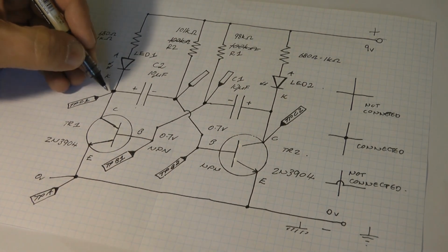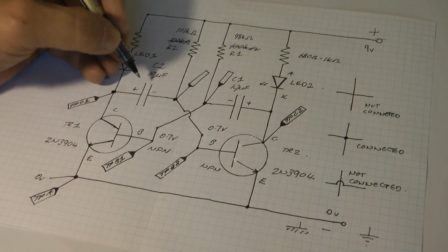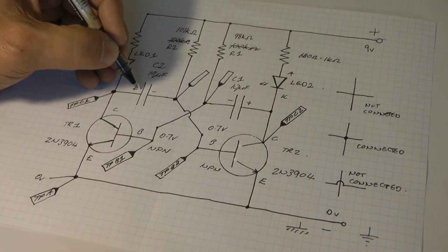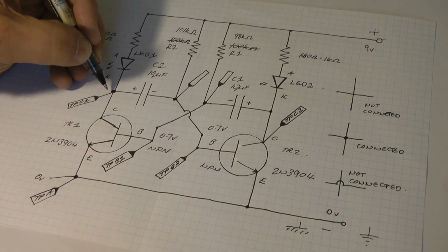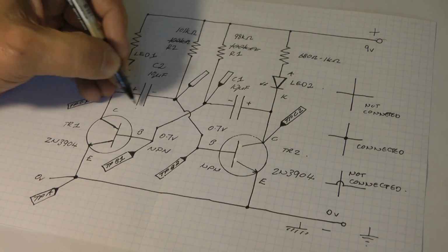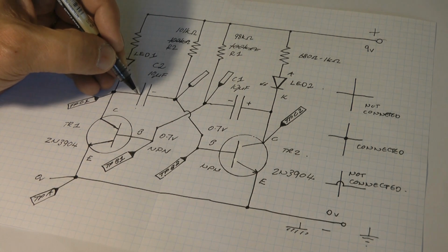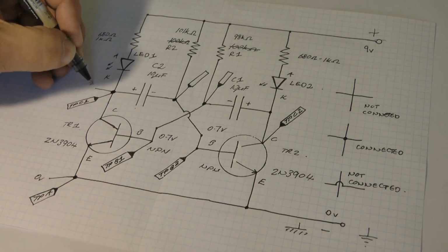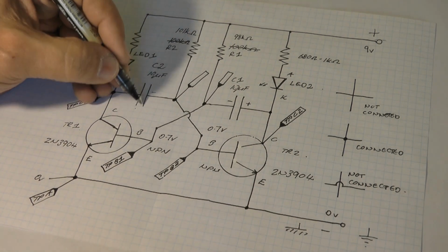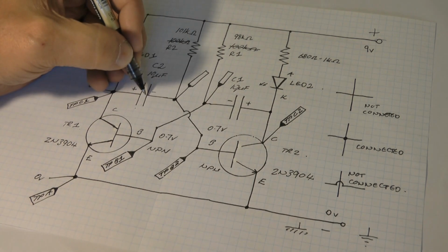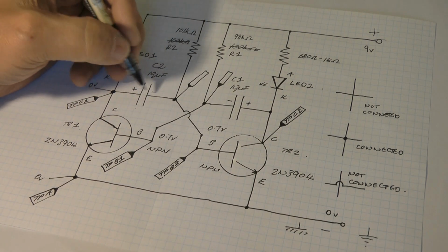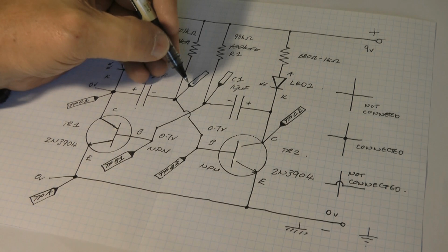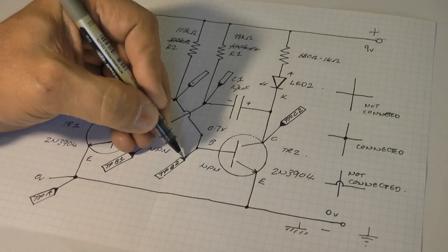Because test point C1 is dropped to 0 volts, whatever voltage was across this capacitor here is now pushed quite deeply into negative territory, because if you have a voltage here, a potential difference across the plates of this capacitor here, and now suddenly you have 0 volts over here, that forces whatever voltage is here to read as a minus voltage. And you can see that minus voltage appears over here, but it also appears over here.